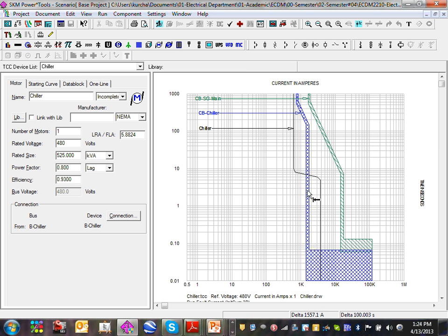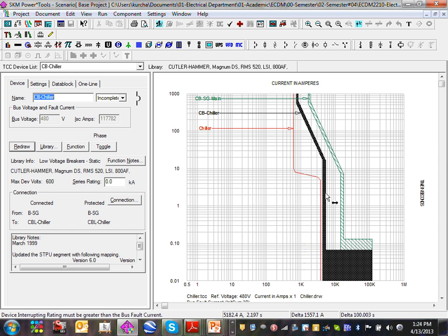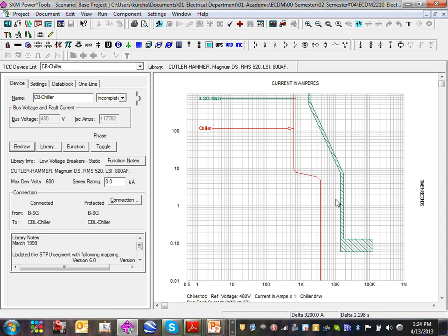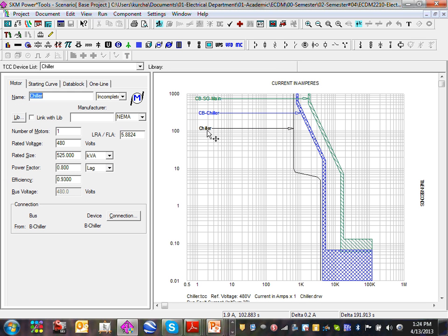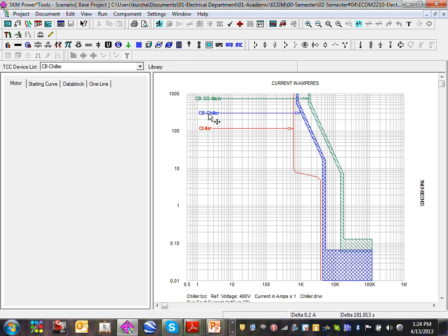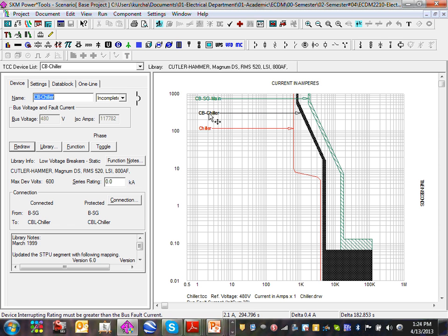So you need to take this leg, can you guys see that, and move it. Move it as far, but if you move it that far, arc flash will burn you, right? You have to move it as close to that red curve as you can without touching it. Why can't I just keep moving it to the left, right, Chad? Because you're having a lot of arc flash. Perfect. So here's the circuit breaker, guys, that protects the chiller and allows the chiller to start and run, which is all you need.